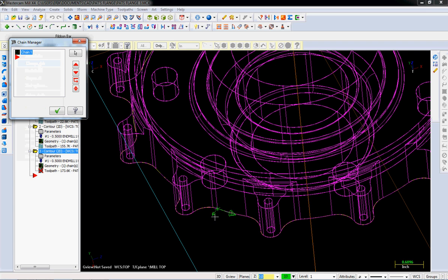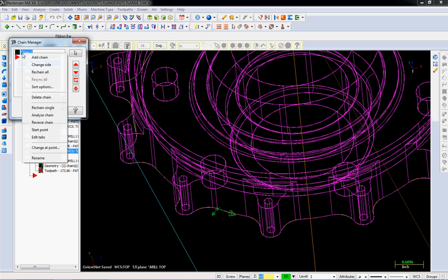But notice, for some reason, Mastercam's not smart enough. It didn't change the direction that we're cutting. I guess we told it the direction, so it's just listening to us blindly, even though we were dumb in the first place. So now we're going to get a conventional cut. If you are making a really wide cut width, cutting steel or some material that's real tolerant to a conventional cut with a good surface finish, that's great. If you're cutting in something that's not going to tolerate that conventional cut and you want a climb cut, this is still not acceptable. Now you're on the right side, getting better, but let's change the direction.